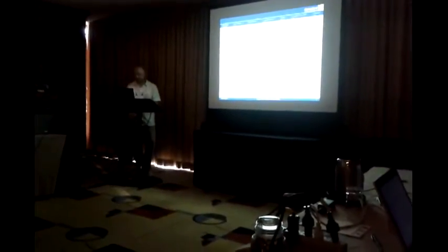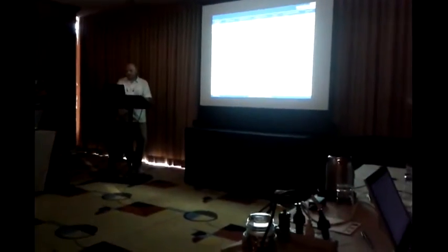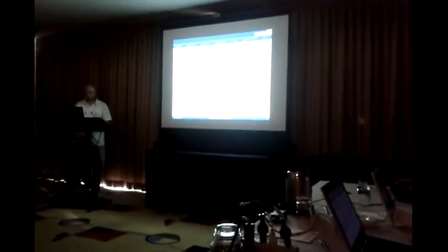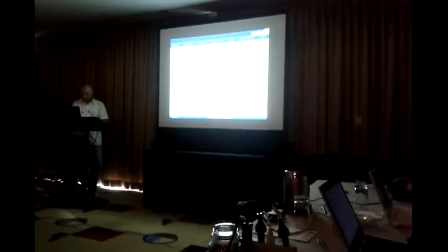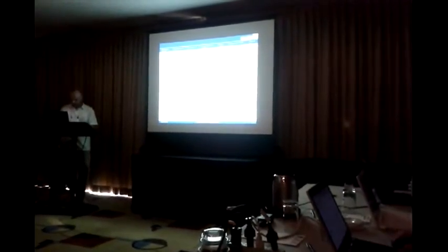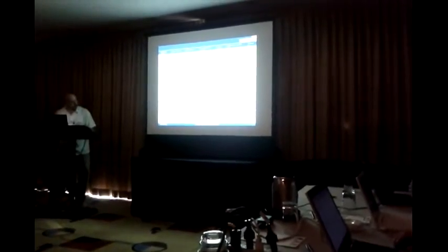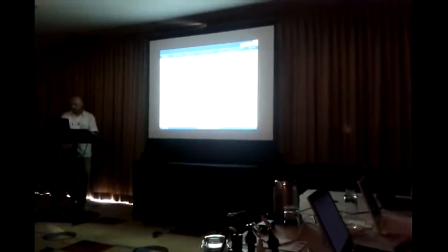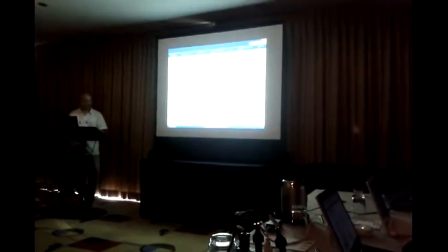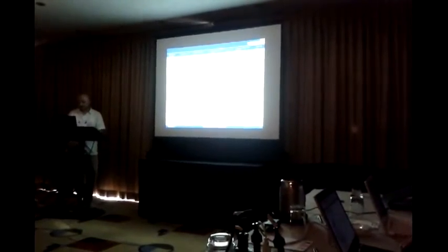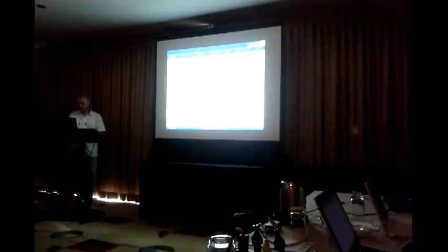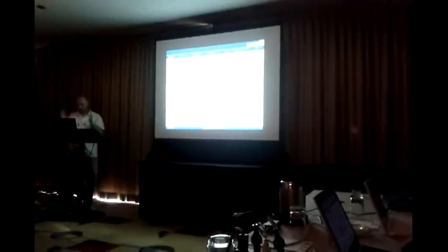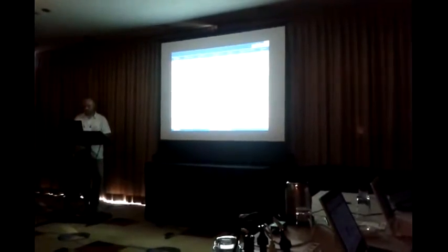In the lower part you see a table for the single PRF radar signals. There are a bunch of different types differing in the PRFs and pulse widths. What is important to understand here is that there are radar types that consist of just 10 pulses, while there are others that are easier to detect because they consist of a much higher number of pulses.